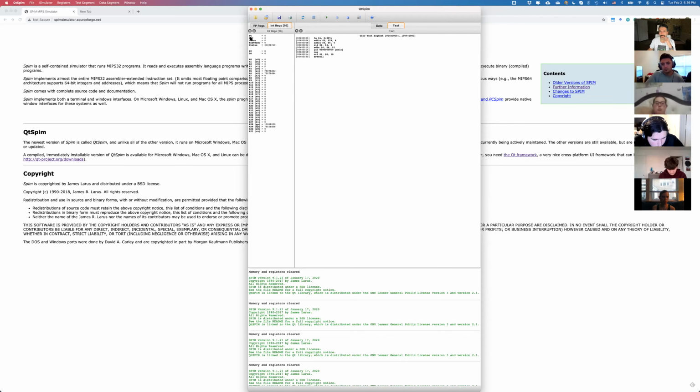EPC and cause: EPC is a special purpose register where, if an exception happens, it saves the location, and the cause register records the cause of the exception.